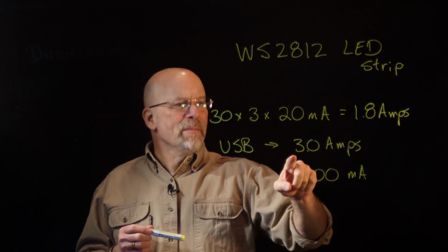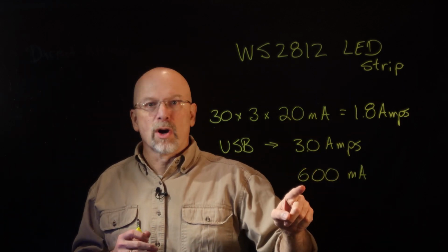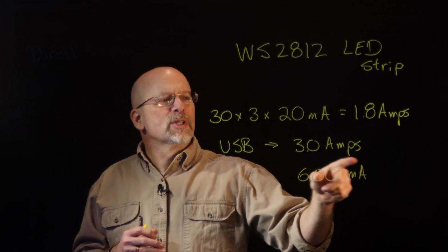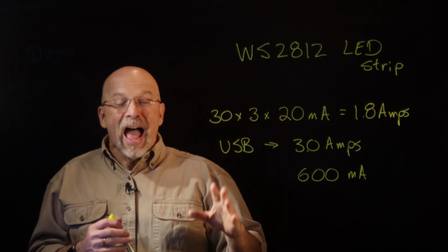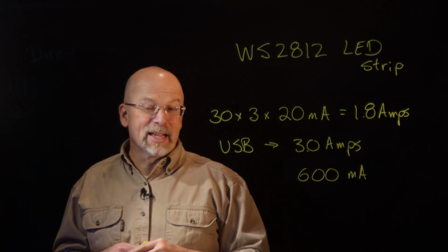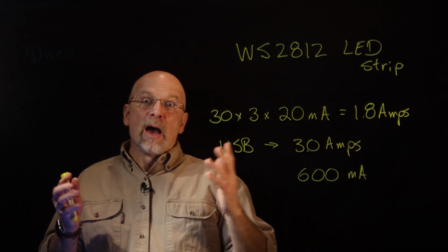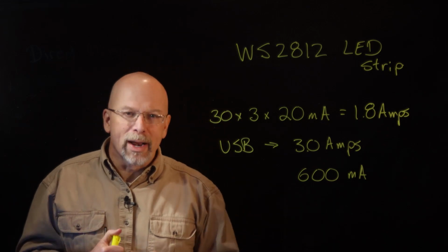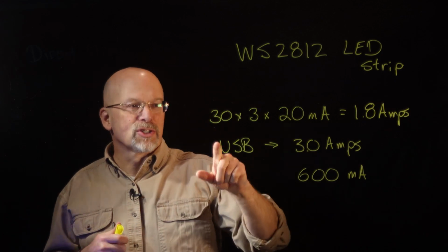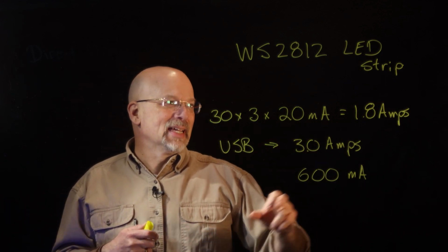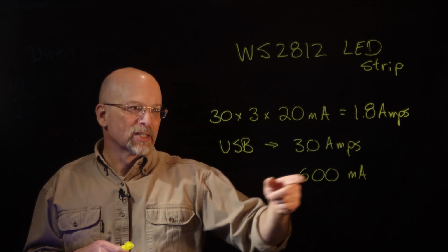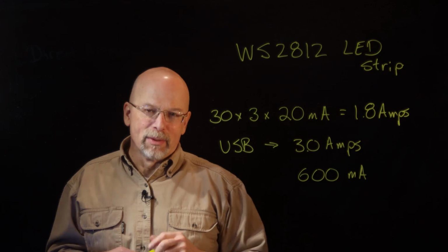So, from this 3 amps, bare bones, we're already pulling away over 0.6 amps. After a while, plugging in monitors and keyboards and so forth, you've chewed into the current that you're asking to draw for those LEDs. And what if I want a longer string, something that's got more LEDs than just 30? If you've got perhaps a 9-foot long string with 90 LEDs, suddenly we're looking at almost 6 amps just for the LEDs, way outpacing what's available from the USB.